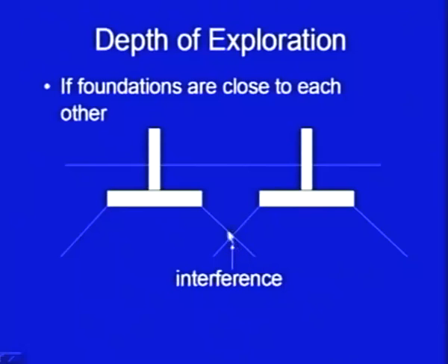Here we have shown these two foundations. If they are close to each other, this is the stress distribution, the stress is being dispersed in this way. So, somewhere here the interference starts. So, in this case you should have much more data available up to much more depth.